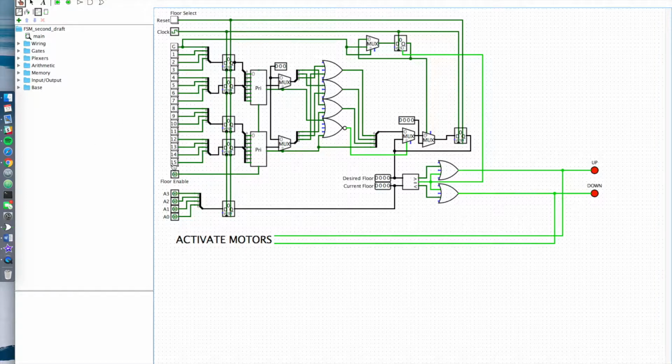For all pins from 0 to 15, you can select a pin, update a register, move through a priority encoder, through some logic, and then get a final output here in the multiplexer, in the final register. What's different that I've added here is, one, I've included inputs for the floors, just with pins. You can set these to whatever you want. This simulates more closely what the actual elevator will give me. And additionally, I've added some logic here that will lock the elevator in a path to ground if ground is selected. Okay. So first I can show that it works normally as intended.